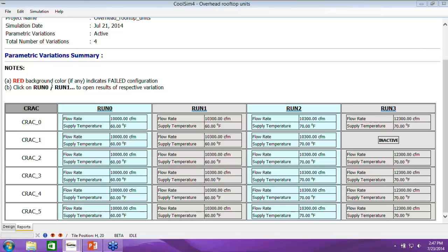And here, again, I ran a series of runs, not just one, but I ran 4. And over here, I left it just the way it was. And then what I started to do is bring up the airflow from the cooling units to try to optimize that RTI. So I brought it up 1,800 CFM roughly, 300 each, to try to improve that. And then I started marching up the temperatures, right? Same as before, same methodology. Get RTI set, then start marching up the hill of supply air temp.